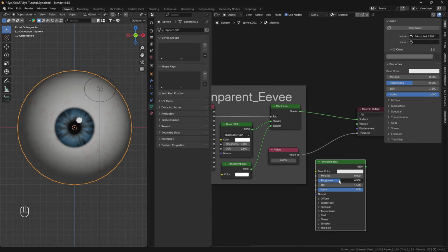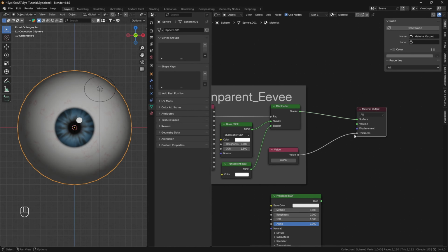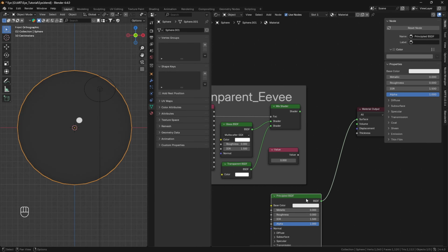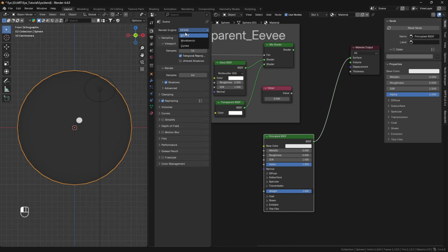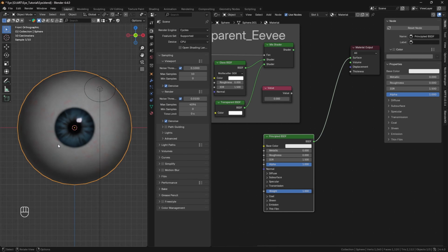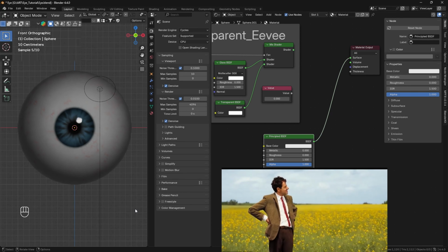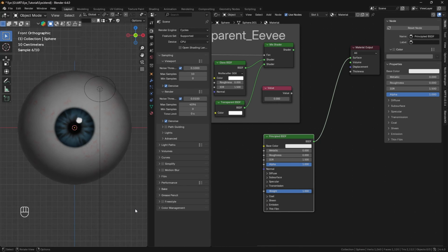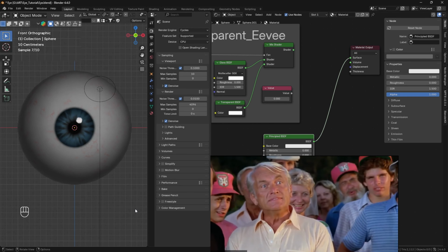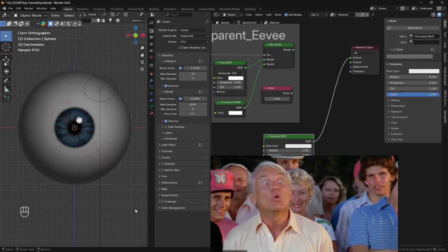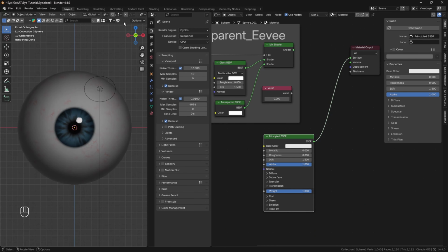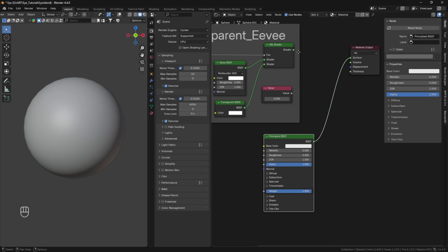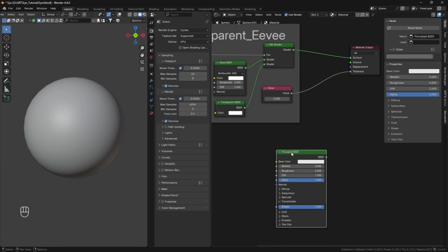Now for the lens of Cycles, just set 0 in the roughness value, and in the transmission slider change the value all the way up to 1. By this we will get the results. Let's test it out. We're waiting. Okay, rendering is done. You can see the result is good. Then again switch back to Eevee, frame the Principled BSDF and give it the name cycle transparent.